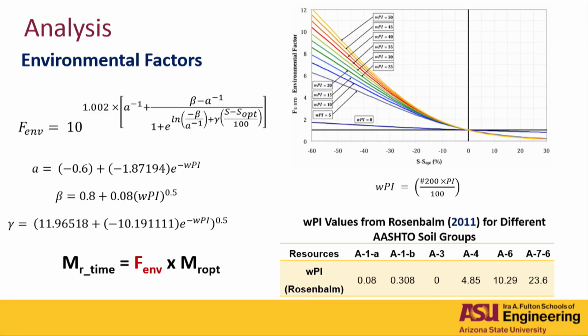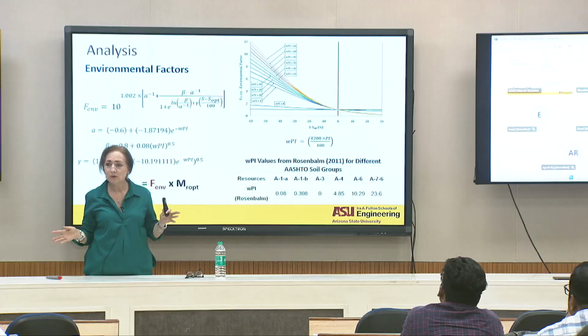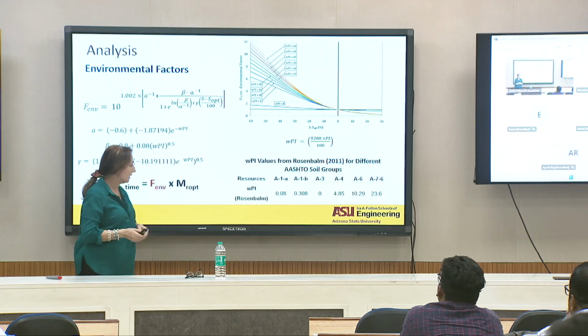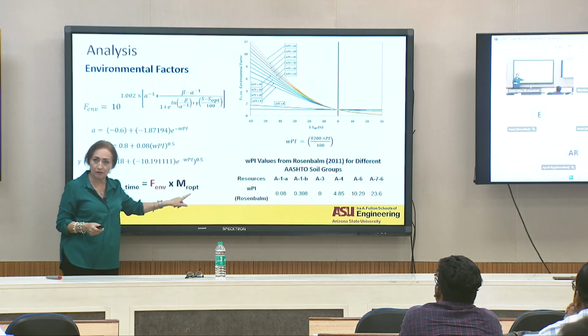So we do have a resilient modulus for the soil that is usually done in the laboratory at one water content condition. We do the resilient modulus at optimum, or we do the resilient modulus soaked, which is 100% saturated, and pretty much stop right there. You don't do more. So you just do one value of the resilient modulus at one condition and use this value for the design procedure forever, for the 30 or 40 years of your pavement. Well, this is the value here. That's your initial value, all right?